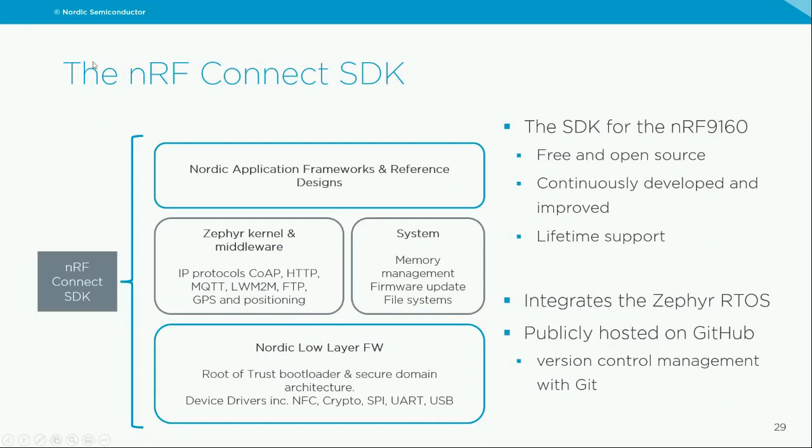So, one quick peek inside the software development kit for the 9160. Inside the SDK, you have our low-layer firmware, including bootloaders and device drivers. We have a real-time operating system called Zephyr, and with Zephyr, all the middleware and all the stacks that run on top of Zephyr, together with all the system management that you will need to run an operating system with all the device drivers. And on top of this, we offer an application framework and also complete reference designs for complete applications, such as an asset tracker or the LTE serial modem.